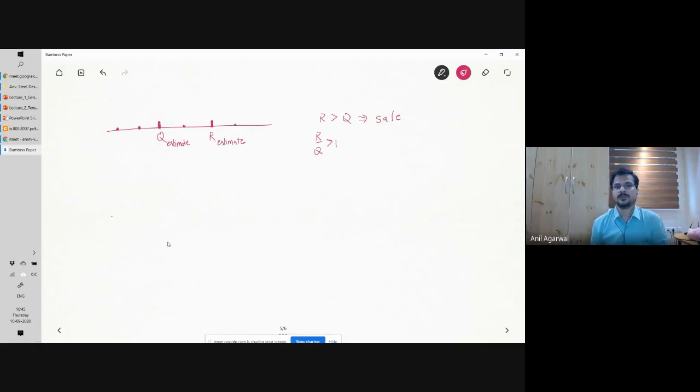Okay. So then what may happen is that if I test, let's say 100 columns, for which all of those 100 columns, I had estimated the capacity to be exactly this R estimate. They are identical columns or identical type of columns, so even with those columns, what will happen is that majority of them, if my understanding of the behavior is correct, will be showing me this much of capacity.